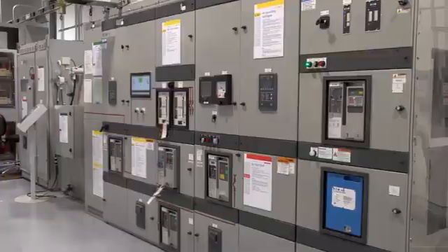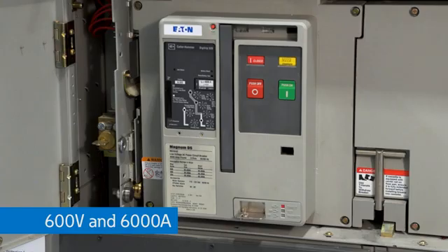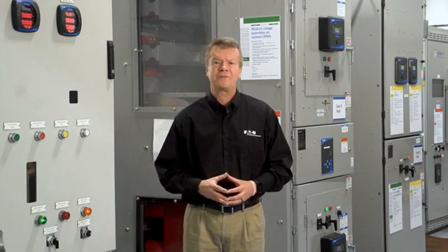Power circuit breakers are designed and engineered specifically for use in low voltage and medium voltage switchgear. The low voltage breakers are available up to 600 volts and 6,000 amperes and up to 200,000 amperes of fault current. And medium voltage breakers are available in 5 kV to 38 kV and 600 to 6,000 amperes. These power circuit breakers have many mechanical parts that need to be exercised, lubricated, and maintained. Most, but not all, are draw-out breakers.